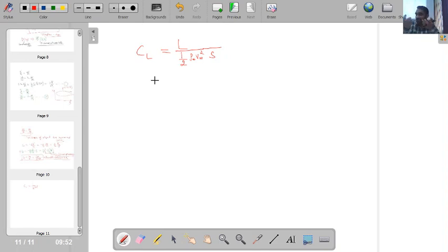So if we have made the analogy for pressure distribution, and as the pressure distribution is not changing, whatever pressure distribution we took for estimation of Cp, the same is the pressure distribution for estimation of lift force also. As these forces originate from the pressure distribution and it remains the same, the way we have calculated the pressure coefficient, in a similar way the lift coefficient will also behave for incompressible and compressible flow situations.